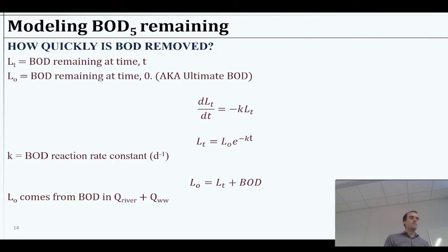What's relevant to it? Okay, so the rate for the BOD, it's the oxygen demand itself, so the deoxygenation, really depends on the amount of BOD that remains, and when I say BOD, biologically degradable stuff, right? Stuff that will cause oxygen demand. Our rate will depend on how much of that is there. That's kind of that total organic carbon assessment. So we could call that TOC or substrate.